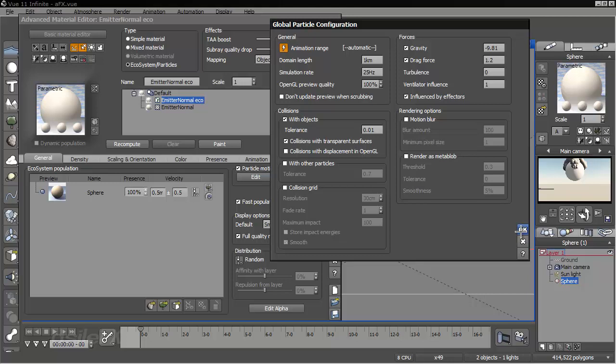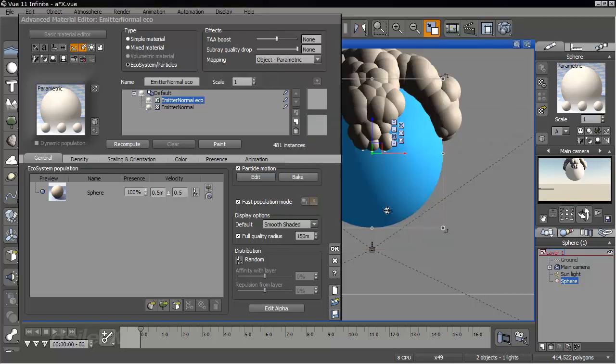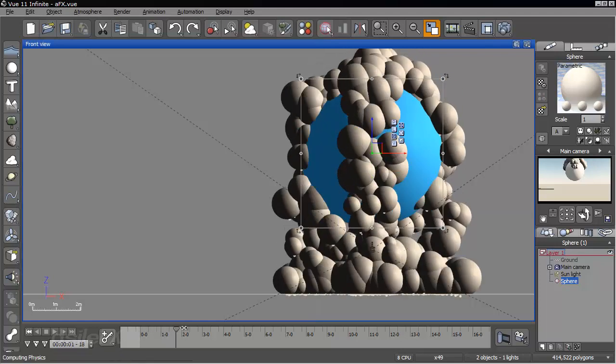So if you notice a lot of particles kind of flying off in directions, or it looks unstable, or some of the sections aren't really doing what the rest of the particles are doing, you can increase the Hertz in order to create a more accurate calculation.